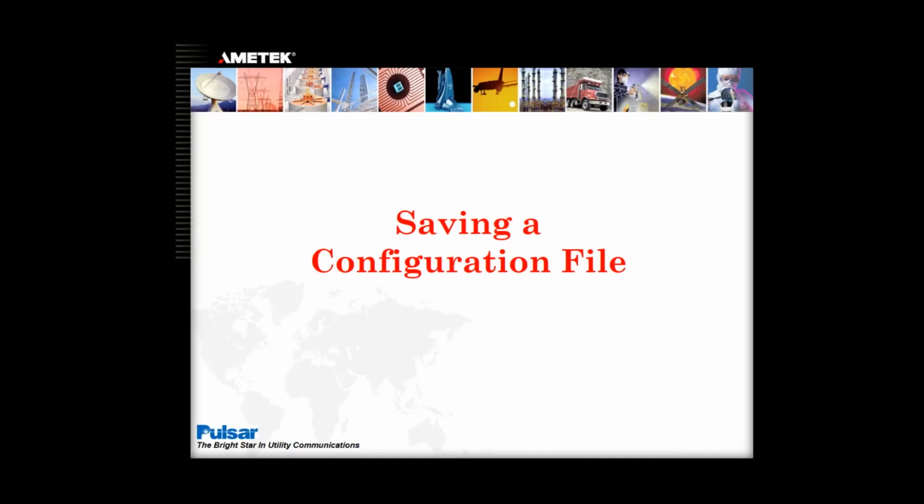Next, we are going to show you how to save your software settings as an XML file for later use, so you may copy them into another UPLC. This is how you would make a backup for a specific UPLC or a default company configuration file. Only the current web page settings, which include pending changes, are saved, not the current settings of the connected UPLC.